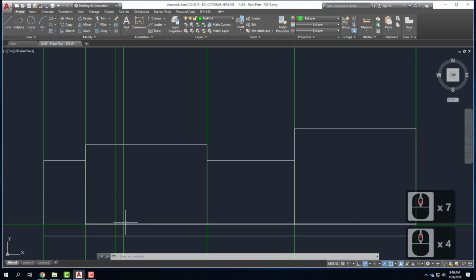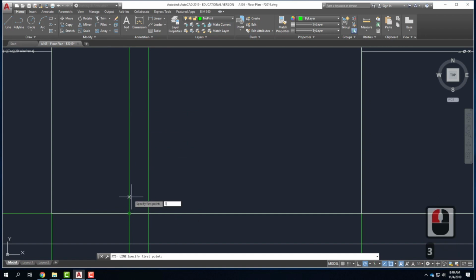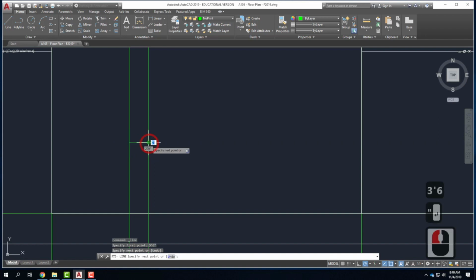So there it is. I need to have an understanding of what that window looks like. So again, that's my floor. I have cabinets. My cabinets would be 3 feet tall. That's a standard cabinet. So I need to start my window above where those cabinets would be in the kitchen. So we'll do it at maybe 3'6". So I'll go ahead and come up here, 3'6". And that's my first line of the window.